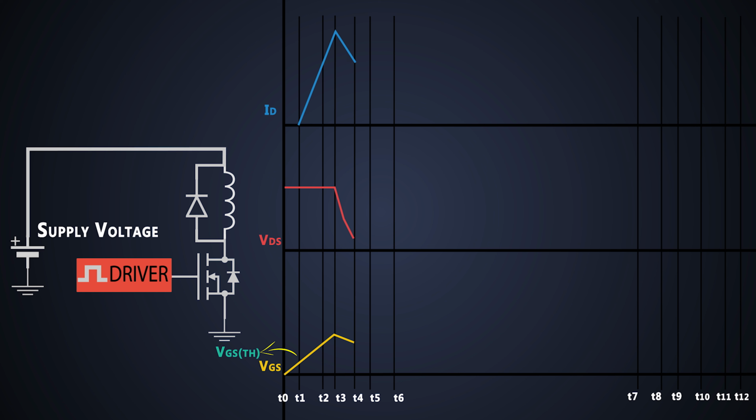If the drain current decreases, the gate source capacitor is discharged via the mirror capacitor, and the gate to source voltage value decreases to the value sufficient to conduct the drain current. Consequently, a sharp drain to source voltage waveform is generated during this period. Well, this sharp change in drain to source voltage causes so many problems.